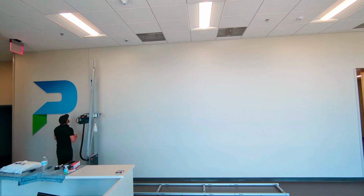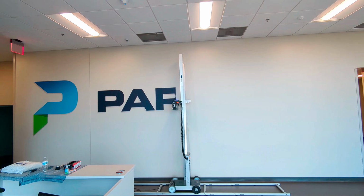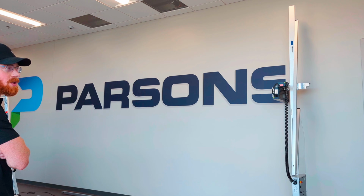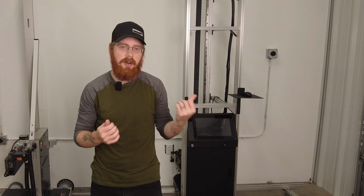So if we had a wave design that was a blank background everywhere else, and we were using skip swath, the printer would only print where it needs to, moving up and down within that printable area and saving us a lot of time. If it was a design like a wave, we might save half of our print time in doing that. But usually with designs, what we're looking at is some kind of logo, maybe with wings coming out to the side, and that saves us about 20 to 30% of our print time. Now, this is a feature that comes standard on the DXonJet that you can turn on and off.